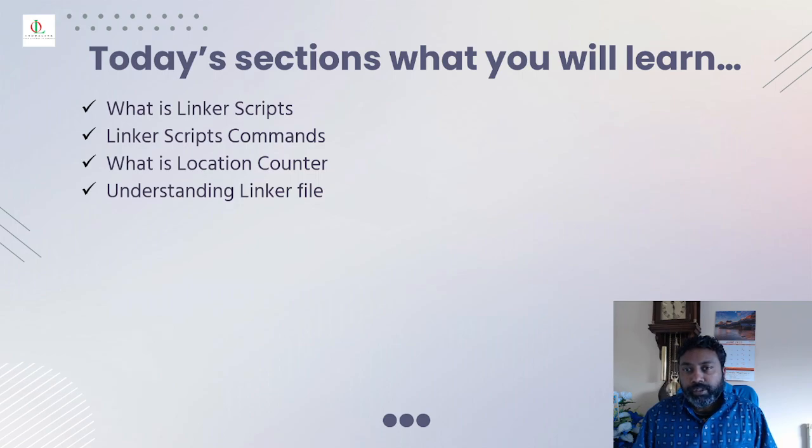And then you will go through the linker file line by line, what it is all about, so that you'll get a more familiar understanding of the linker file. Like in the previous session, the startup file and the linker description file are the two most important things that any embedded system design engineer should be aware of, because once you know these two concepts, you can go and modify these two files and use them in your own projects. So from the previous session, you can write your own startup file. Likewise, at the end of today's session, you can go and modify and write your own linker script.